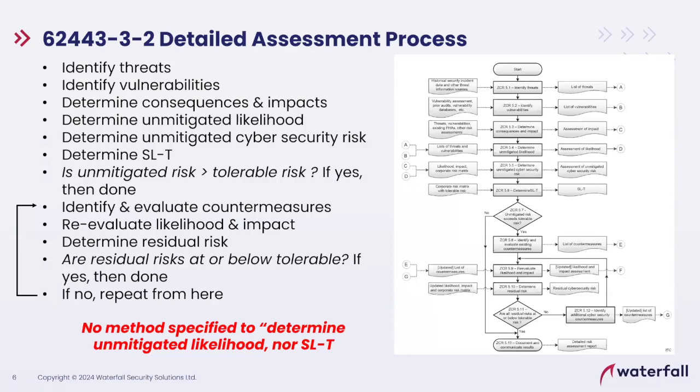And 62443 uses the word vulnerability in a very confusing way. I'm sorry, the drafting team should change that word. They don't mean software defects for which there are patches. That's not what they mean by vulnerabilities. By vulnerability, they mean any opportunity to attack a system. It might be a weak password. It might be a misconfigured firewall. All of these are vulnerabilities. Identify attack opportunities. Determine consequences. Determine how important these attack opportunities are because of the consequences they can bring about, and so on.